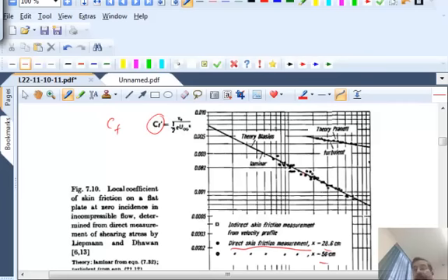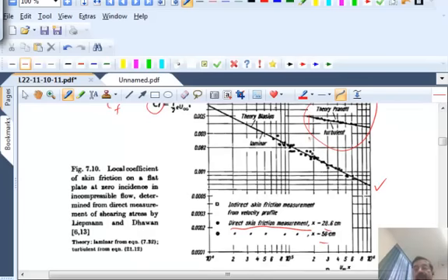You find that the agreement is excellent for the laminar one. But it does become turbulent at a Reynolds number of about 10 to the 5, 2 times 10 to the 5. Beyond this, this graph can extend because it's a stability problem. Sometimes you may be able to realize laminar flow at an even higher Reynolds number if you don't have any disturbances.